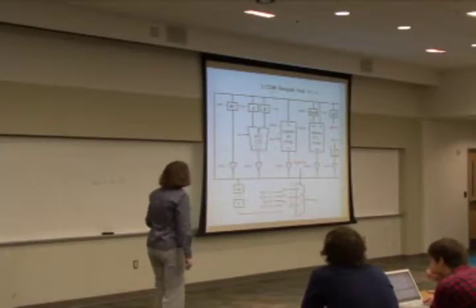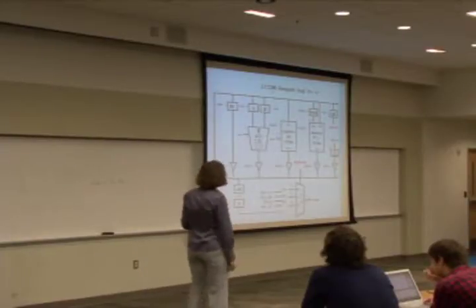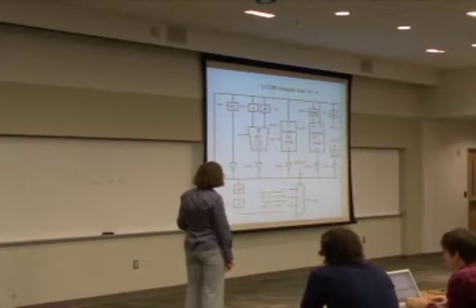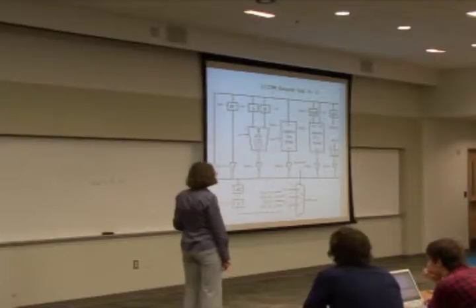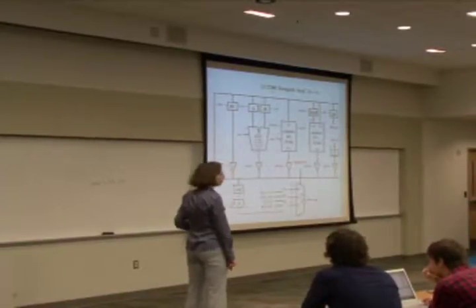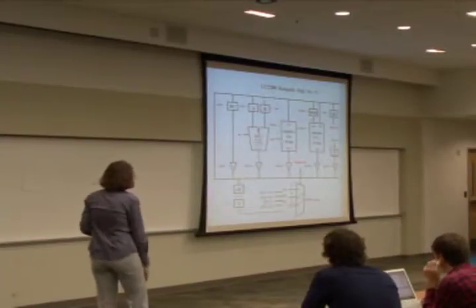So how do we store Rx into A? Well, the similar steps as before. We set the register selector to 0, 0. Then we read the content of IR on addresses 27 to 24. And that's our address that we activate here. And we read what is there. We let it on the bus and load it into A.